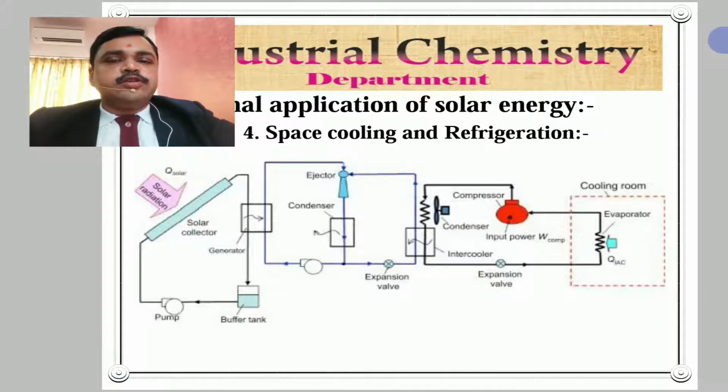The rich solution flowing from the absorber to the generator is usually heated in a heat exchanger by the weak solution draining from the generator, which helps to improve the performance of the cycle.